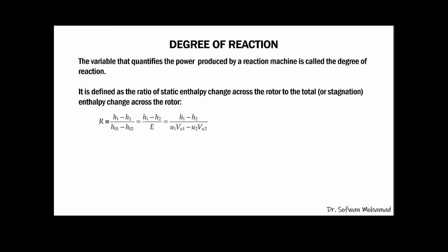Capital R is the reaction or degree of reaction. It's equal to H1 minus H2 over H01 minus H02. H0 is the stagnation enthalpy, H is the enthalpy.